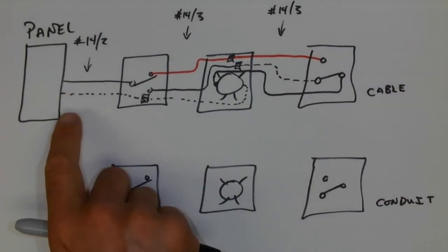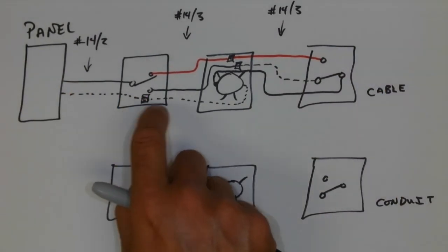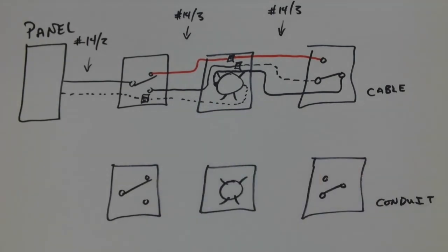Are you going to rewire everything so that it's switch, switch, light? That sounds like a behemoth amount of work. It would probably be substantially easier to remember or understand the other circuit arrangements that are permissible. And as long as they were originally installed pre-2018, it's acceptable to continue using them.